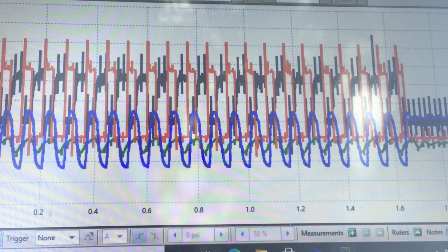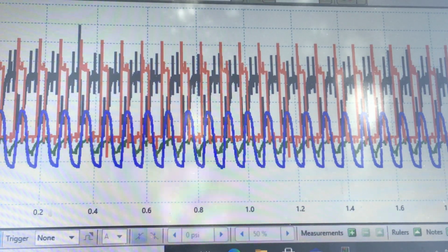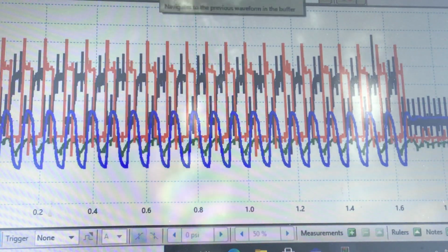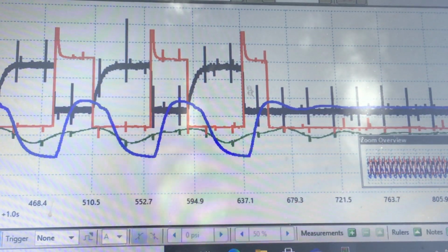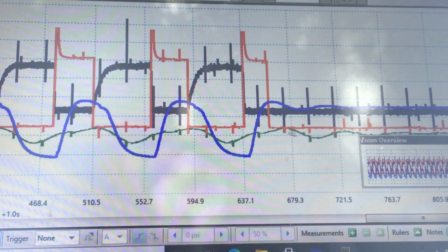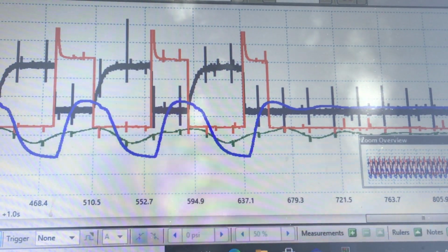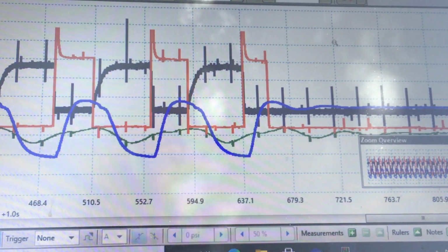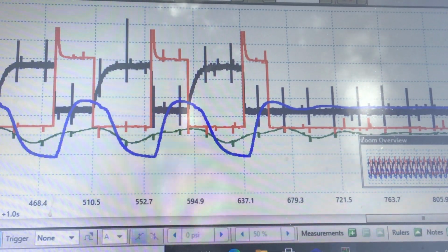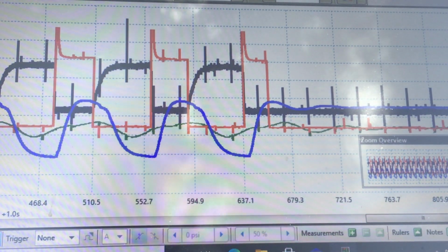Now here's where I disconnected. Okay, that's right here. We can see something happen. We had a little disconnect. This would definitely mean a broken connection here. We stopped. We had no power to the PCM because the system was broken at the purge solenoid. So current stops flowing, vacuum stops flowing into the evap system, and it looks like the fuel tank pressure sensor validated that.